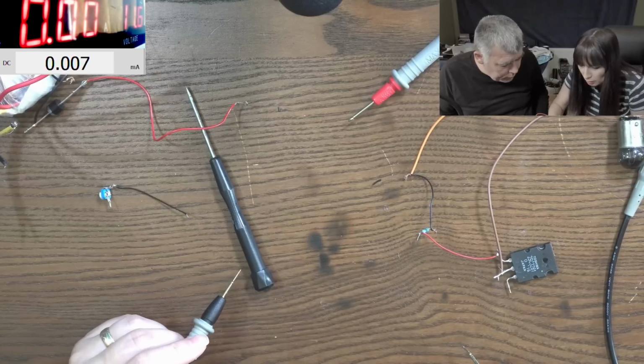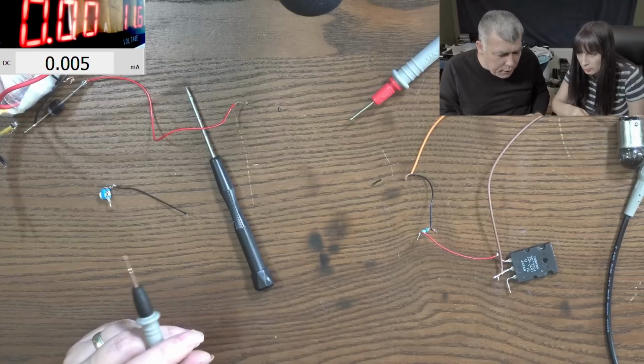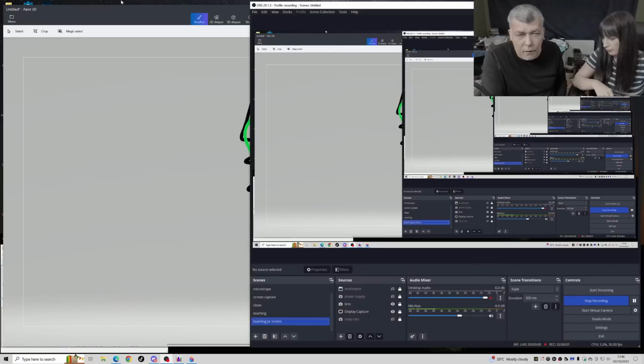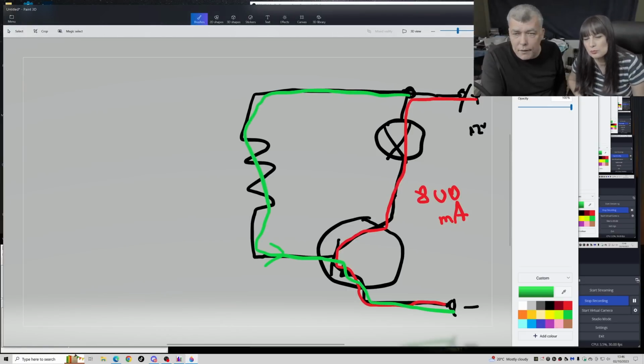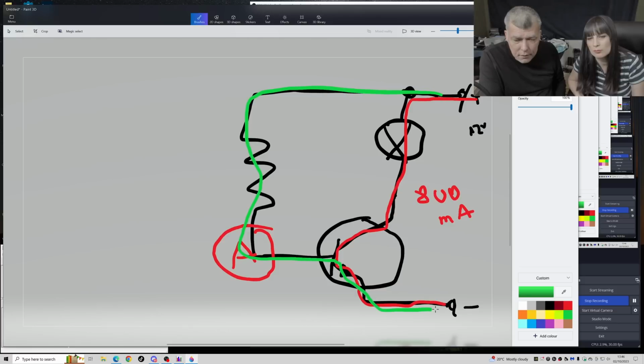How do you check a current? We spoke about that. How are we testing the current on a circuit? I said we are inserting the ammeter in serial mode with the circuit we want to check. So we're gonna have a current flow through the resistor and the ammeter. So that's how we will know what current is there. So the ammeter will be in serial mode. Okay. You understand? Okay. Let's do it.